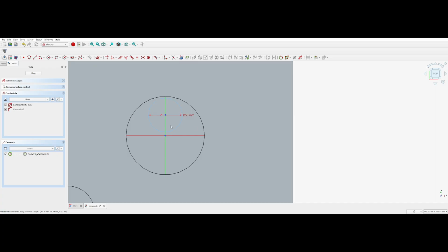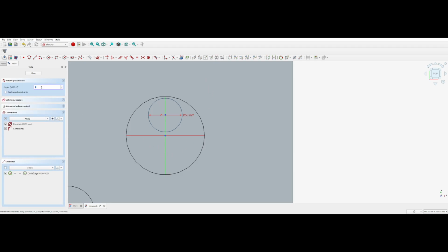And then if you want them to be arrayed around a point, it's going to be similar to creating copies in a row, except this is a polar array and transform, which is this one. So again, let's set our copies here. We know that 3 is going to create 4, but we only want 2 copies.